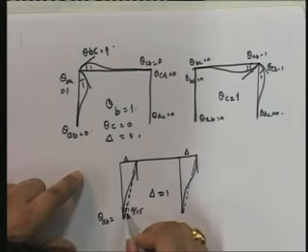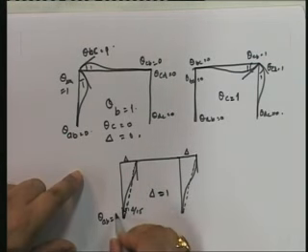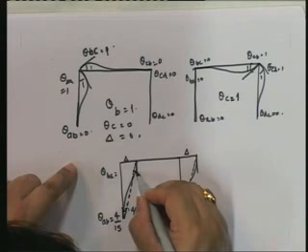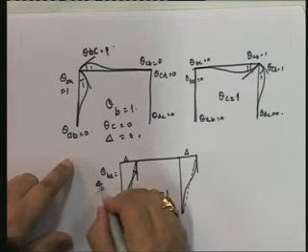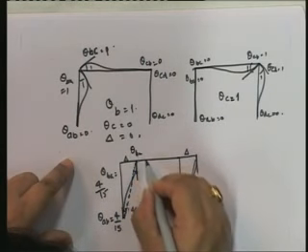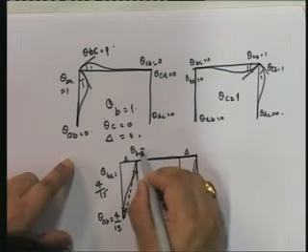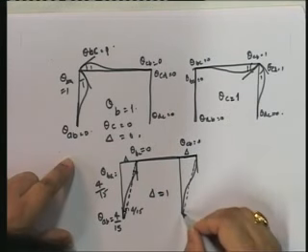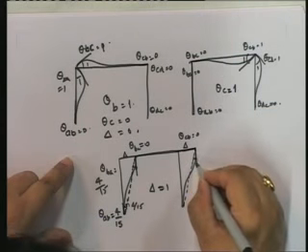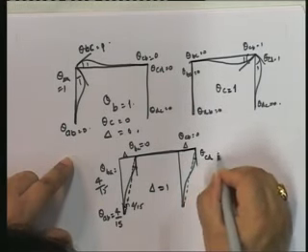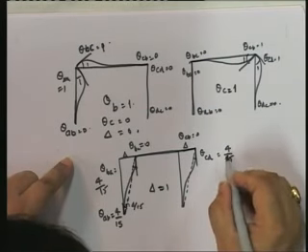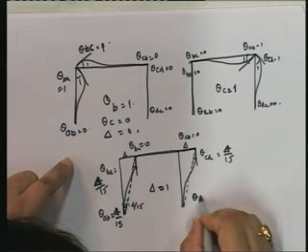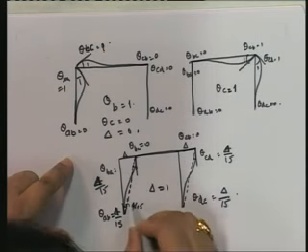So theta BA, now look at it, from the chord to the tangent anti-clockwise, so it's positive delta by 15. What about theta BC? From the chord to the tangent, 0. Theta CB is equal to 0. And from the chord to the tangent, anti-clockwise, positive, theta CD is equal to delta by 15. And DC delta by 15.